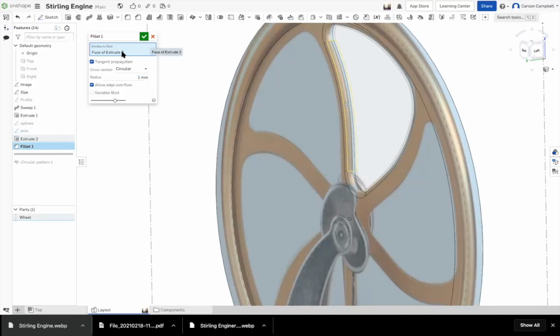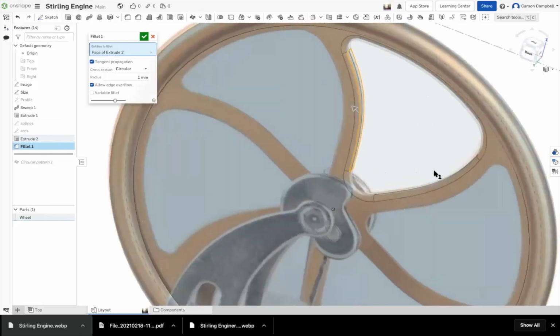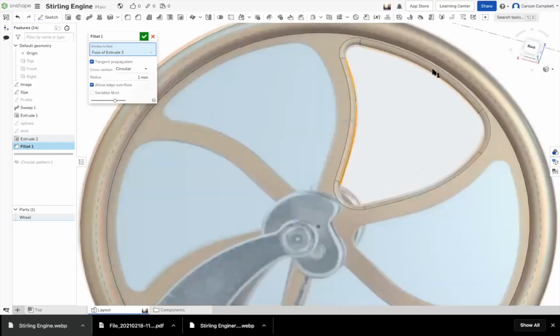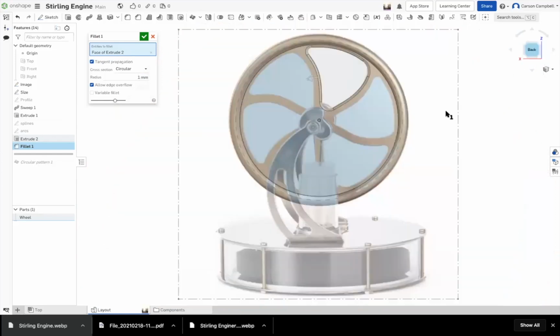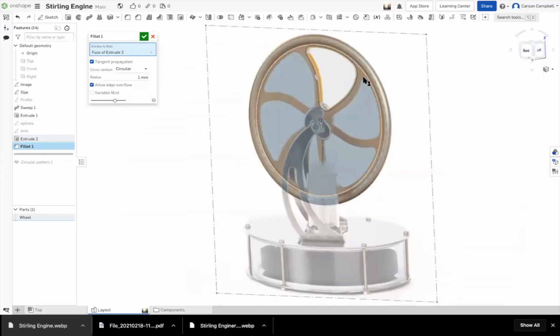Now the other side of this is when you pick that one face, you want to pick one of the biggest faces. Those things that are very big tend to stay around longer, making it more robust. I could go in and pick an arc, but if the guy gets rid of the arc, then the fillet fails. So I'm constantly thinking, what's the biggest? What's going to stick around?